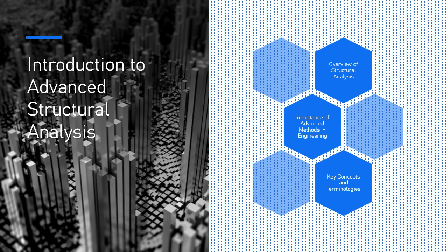Indeterminate structures. These structures cannot be fully analyzed using basic static equilibrium equations due to the lack of enough independent equations. As a result, advanced methods like the finite element method, FEM, and matrix methods are essential for solving these systems, particularly for large-scale and complex structures like high-rise buildings or bridges.